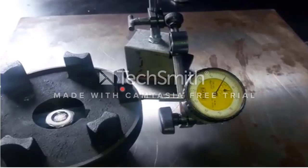Then you rotate this disc. By rotating the disc, if there is variation in the curvature, it will be shown here. If it is a small variation, it can be ignored. If it has a huge variation, then this piece will be rejected. So guys, this is the application of the dial gauge.